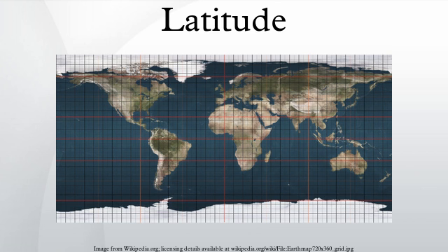Meridian distance on the sphere. On the sphere the normal passes through the center and the latitude is therefore equal to the angle subtended at the center by the meridian arc from the equator to the point concerned. If the meridian distance is denoted by m, then m = rφ, where r denotes the mean radius of the Earth. R is equal to 6,371 km or 3,959 miles.